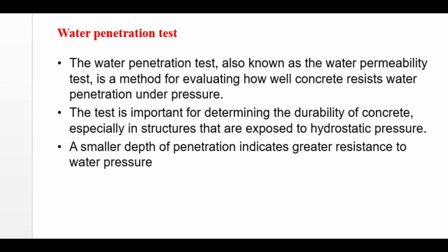Water permeability test. The water permeability test measures how well the concrete resists water penetration under hydrostatic pressure. This test is important for determining the durability of concrete, especially in structures that are exposed to high water pressure. First you need to prepare the specimen: cast and cure the concrete specimen for 28 days. Place the specimen in the test apparatus between 2 flanges and a circular gasket, and then apply water pressure to the specimen in stages, increasing the pressure over time.